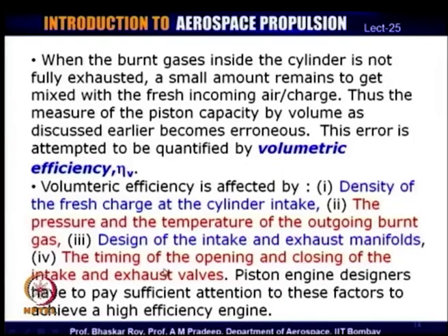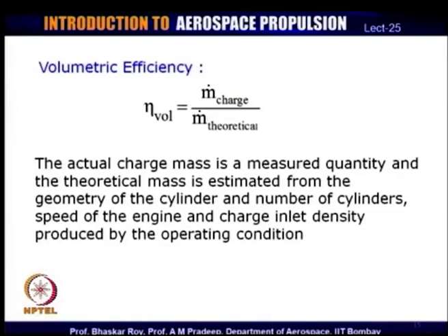This is the engineering that needs to be engineered into this particular piston cylinder arrangement, otherwise it will affect the volumetric efficiency, and this needs to be given sufficient attention by the piston designers. Otherwise, the volumetric efficiency as it is defined now would be coming into the picture, and it is simply defined as the charge that is coming in or the charge that is now available divided by the theoretical charge which we assume to be effective in the cylinder. So, the ratio of the two is the volumetric efficiency.